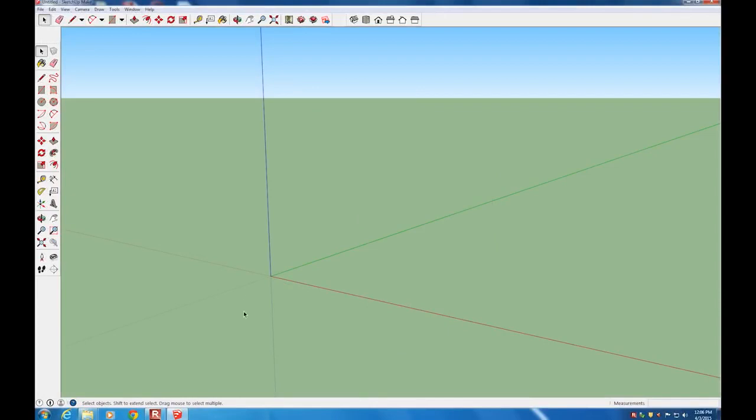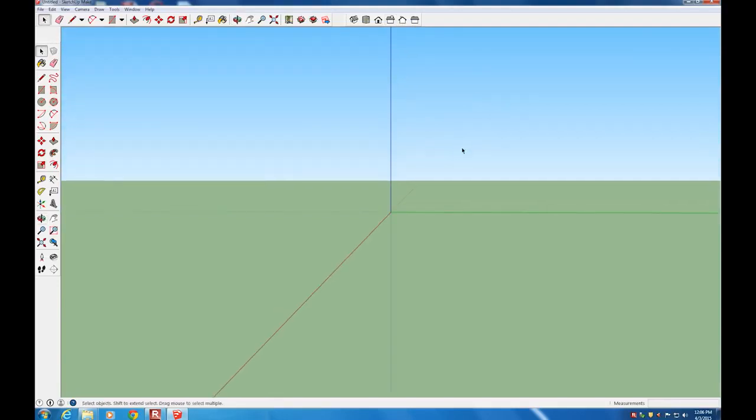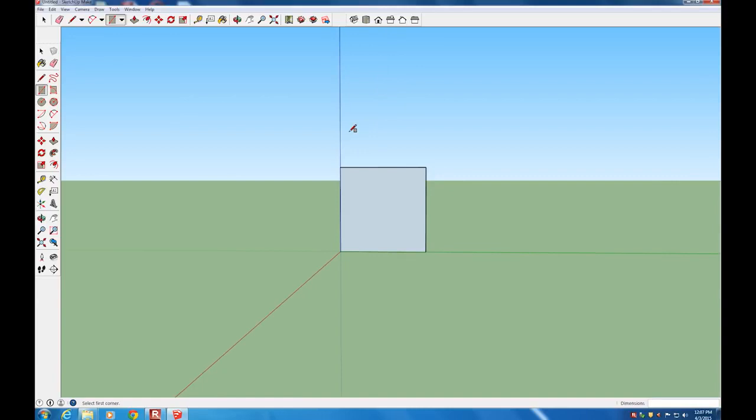So we're going to start drawing the chair. So to start, we're going to go to the right view. So go up to the Camera Views toolbar, click on Right, and that gets us close to the orthogonal plane that we want to be in for drawing from the side. And then I click on the Rectangle tool. Come back over to the center of the screen, click on the origin. You notice the little yellow inference point appears, and then click and start dragging out the direction you want your rectangle to go, and then type the dimensions. In this case, 0.5 meters by 0.5 meters. So I type in 0.5, 0.5, click Enter, and the rectangle is created. We can zoom in for a closer look on that.